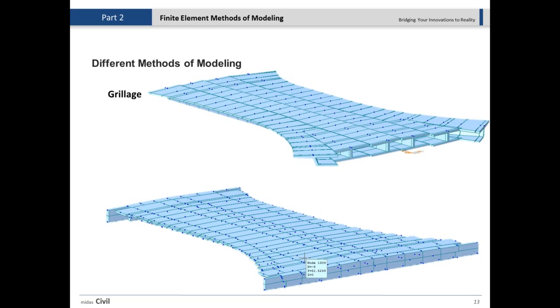The way that he did it, he determined the node locations, then created the elements and their cross sections, and assigned the cross section for the transverse elements as well. Then he applied the loads. Here we can apply the live load, dead load, and post-tensioning on those elements, running different post-tensioning tendons through different locations, and finally get the results.